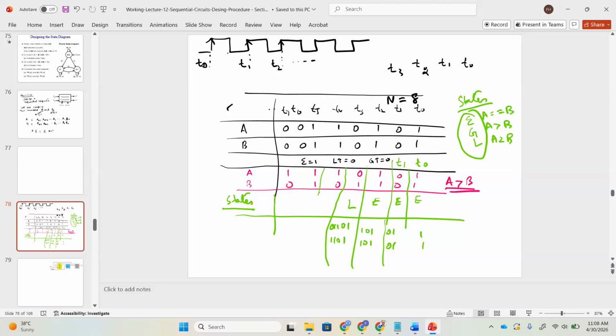Okay, now if I move to the other bits, in this case we are comparing five bits. What will be the answer? Can anyone answer? Greater than. It will be A greater than B. Now this is a more complicated case. If I'm at time t6, now I'm comparing 1 and 1. What should be my next state? Greater than. Yes, it will still be greater, because though AI is equal to BI, based on our previous result it will still be greater. You got it or not got it? Because it's based on the previous state.